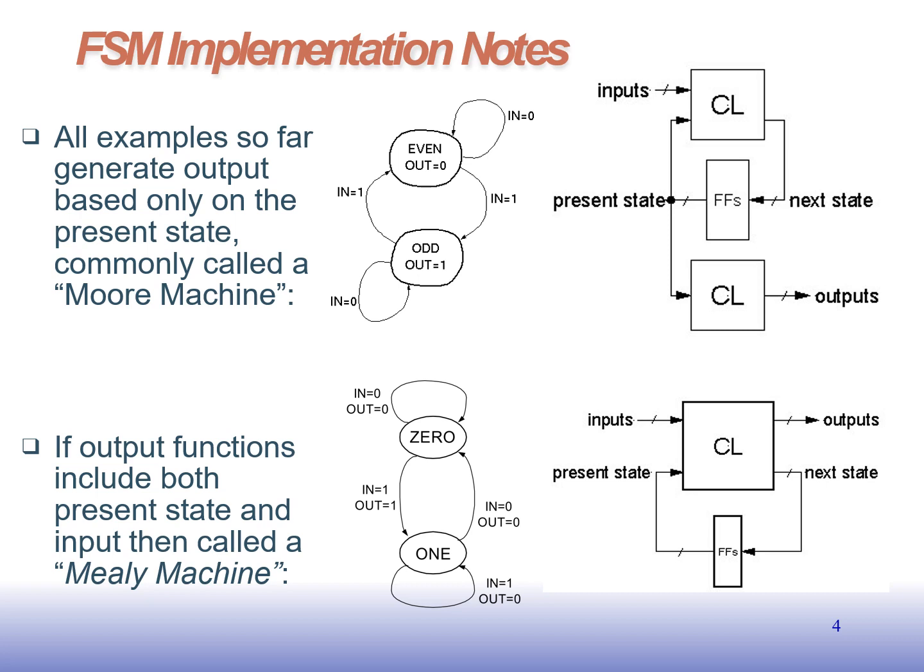Look at this state diagram transferred into the structure. We have a combinational circuit with inputs and present state. Depending upon the input and the present state, the output is delivered and it goes to the next state. The states can be represented in the form of flip-flops. So this is the Mealy machine.